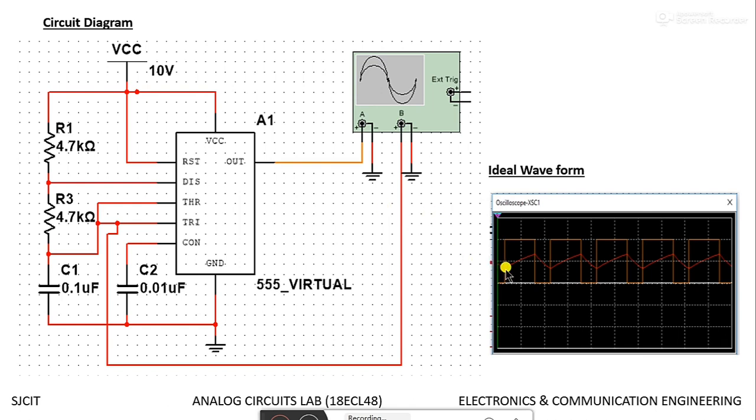Ideal waveform. This is the rectangular pulse which is coming at the output. The triggering is taking place at 1/3 of VCC to 2/3 of VCC, and the duty cycle of this design is 66.66% duty cycle. Let's go for the simulation.